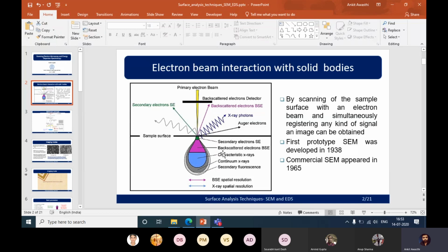But the main thing, Vishnu, I want to mention is that EDS is not that good for composition analysis. You can compare the results of different experiments under different conditions, but if you need exact composition results, I will say it's not better to go with this technique. You can prefer some other techniques. So it is good only for comparison, qualitative analysis, and you can get an idea about some microns.